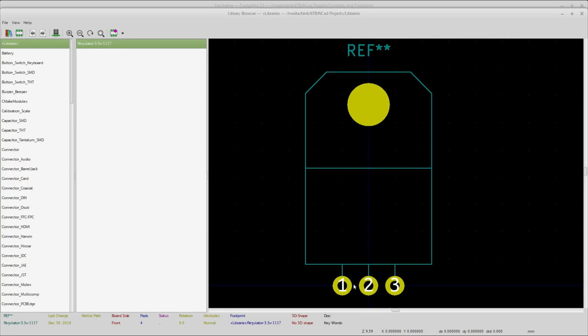Down here are your pins, labeled correctly. Everything matches with the data sheet. This is a hole that will go into the PCB, drilled through, that you'll put a fastener in. And this is kind of the rough outline of the actual item. But again, it's just the stuff that's printed on the flat circuit board and the holes that go through in the copper that's placed on it.